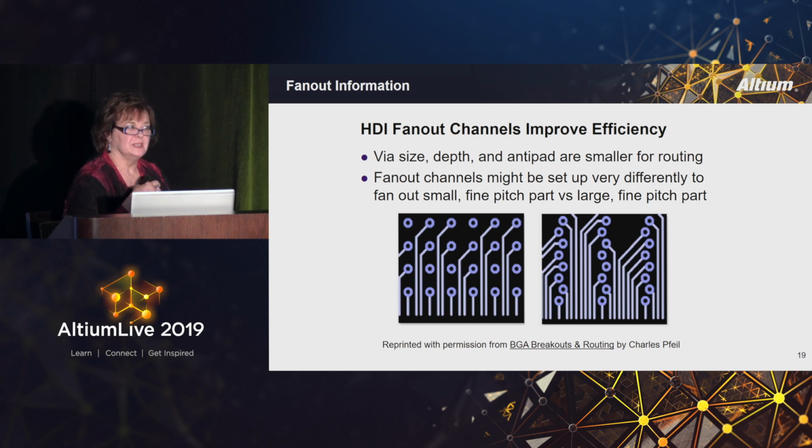HDI is the technology that goes with microvias. Microvias are the actual holes. HDI is everything else: the thin dielectrics, the small holes, the small traces, all that kind of stuff. That's what HDI is, as opposed to microvias. So for HDI, you want the via size, the depth, and the anti-pad to be smaller.